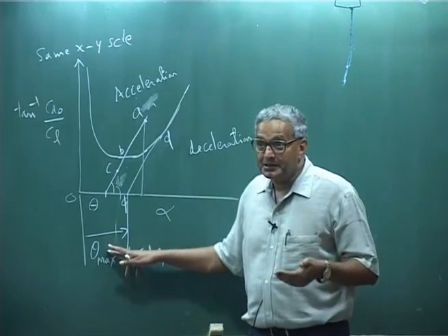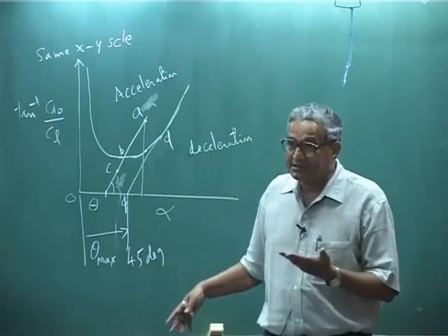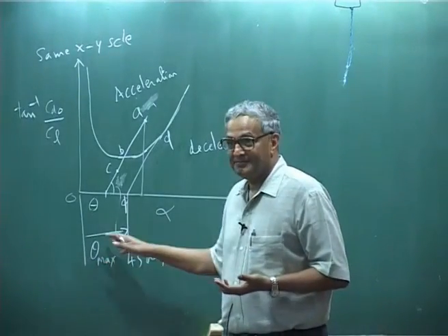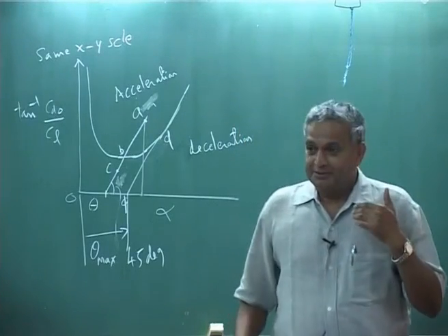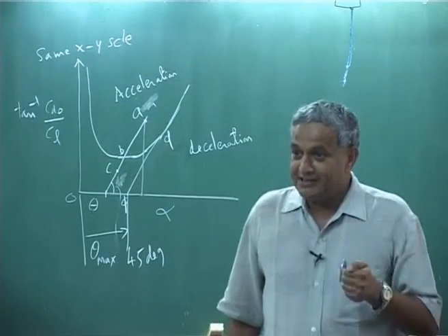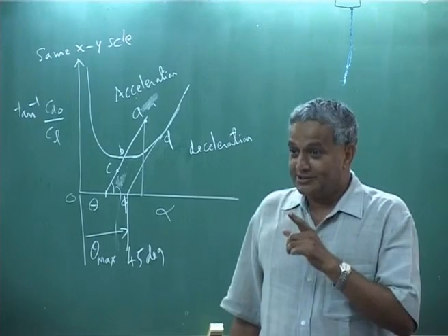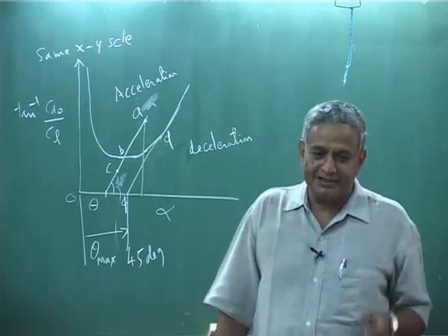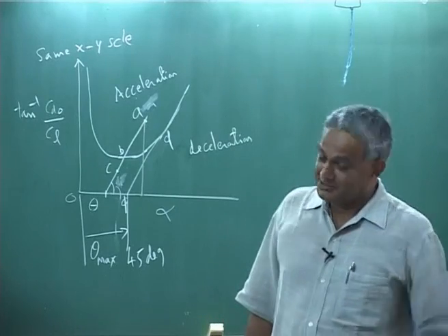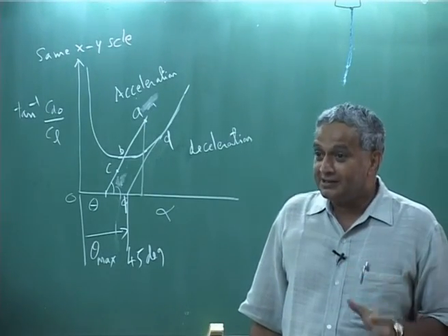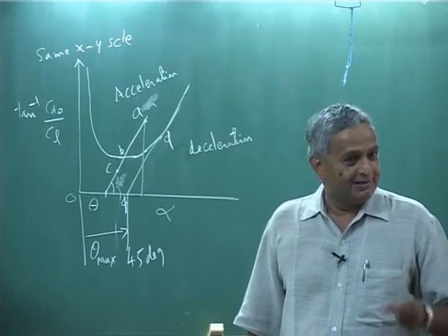He may be operating at a pitch angle larger than this. Usually that is what happens. The moment the engine fails, the pilot is told to dump the collective, that means reduce the collective angle immediately. Otherwise, if you hold it there, the rotor will stop.